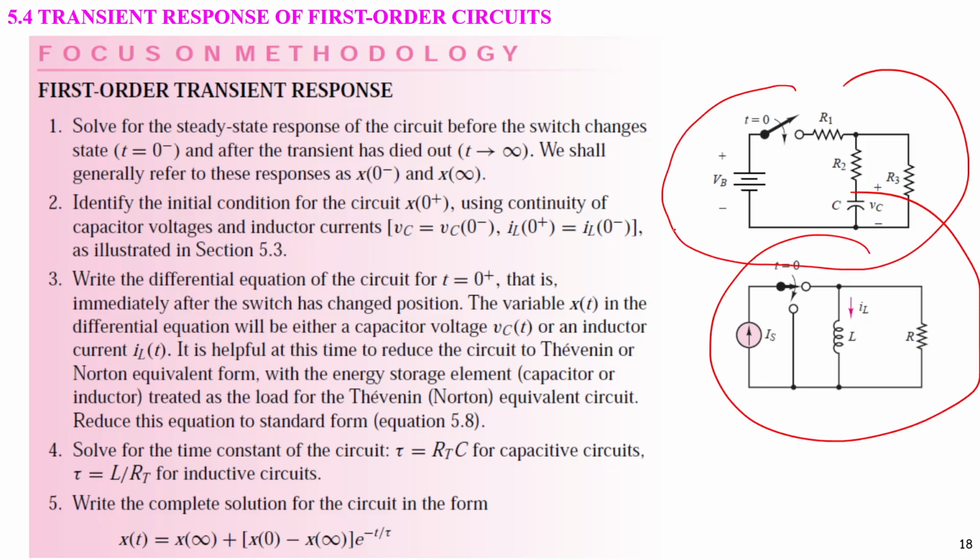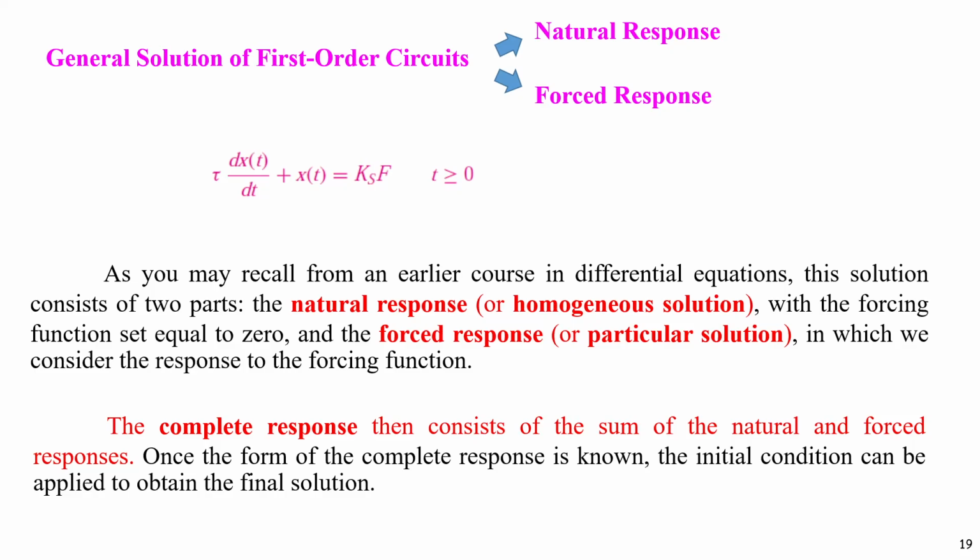How to construct the equation of the circuit by KVL or KCL that we learned before midterm, right? Okay. Then we will get this type of equation to solve. We can separate into natural response and forced response, or we can just rearrange it and integrate, right? Rearrange it into maybe only di or only dv or only dt, and then we integrate two sides of the equation and we get the solution.